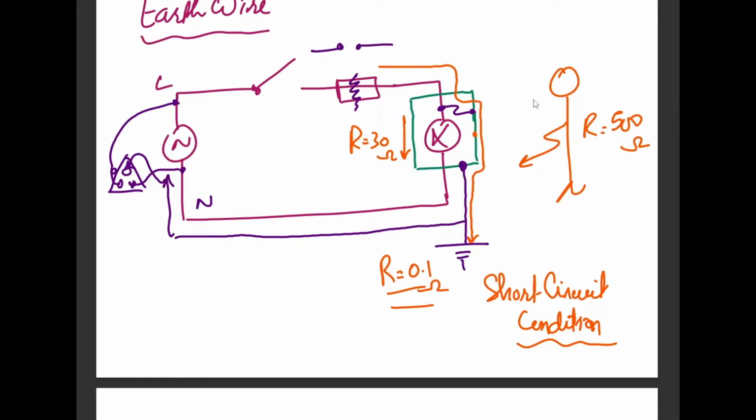So when the operator comes close to the machine and tries to switch it on and off again, the machine won't turn on. Then he will know that either the fuse has broken down or there is something wrong with the appliance. So he will open up the machine and see whether the fuse is damaged or not. If the fuse is damaged, that means that the appliance is experiencing a short circuit. If the fuse is not damaged, that means that there is some actual problem with the rest of the circuit, right? So it can be worked on.